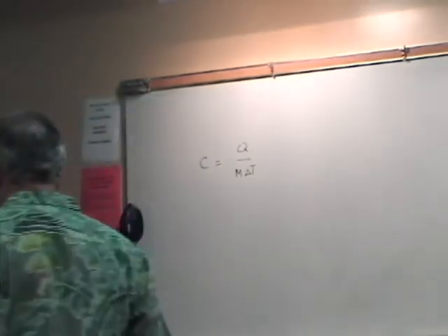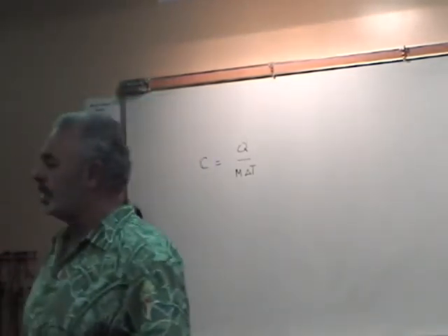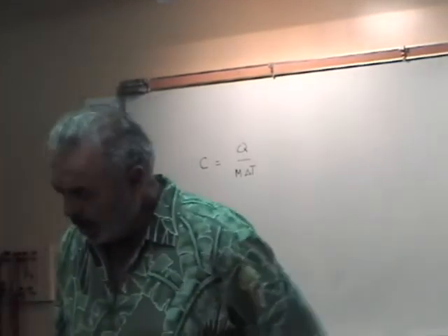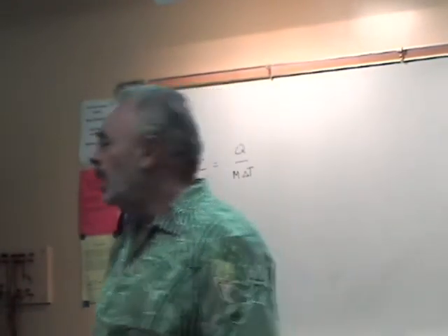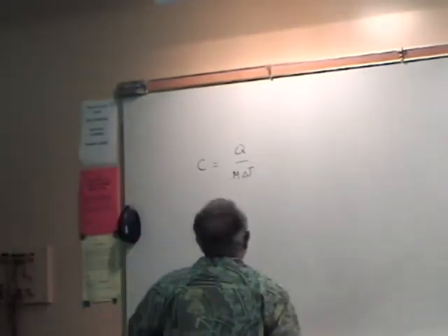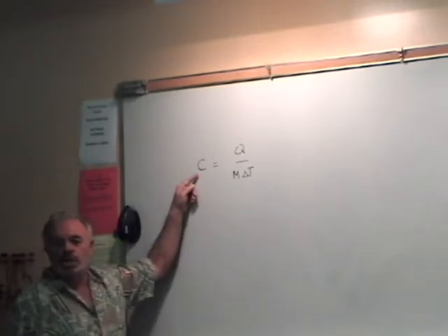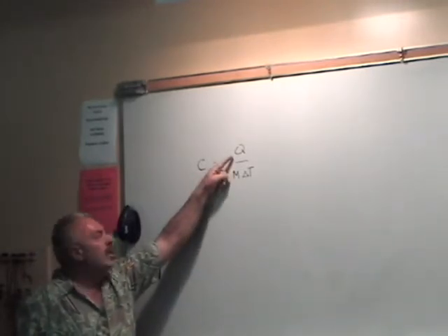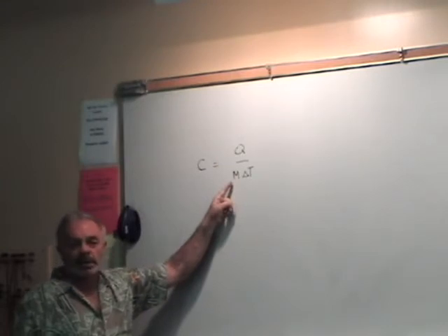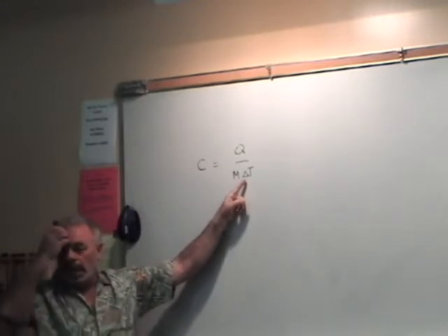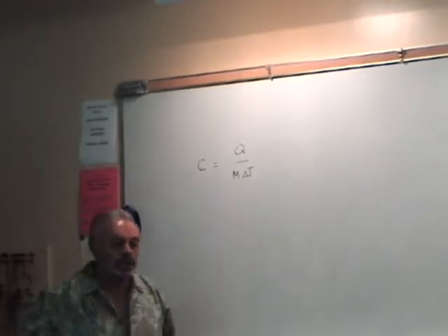And now, as a more broadened statement, let's talk about other objects, not just gases, but maybe solid surfaces, like a block of metal. Then it has a specific heat, which experimentally you can determine very easily by putting a known quantity of heat into this mass of material and measuring the temperature change caused thereby.